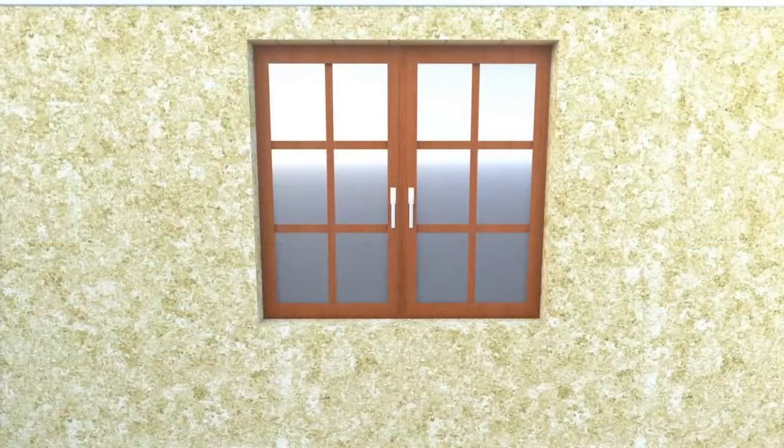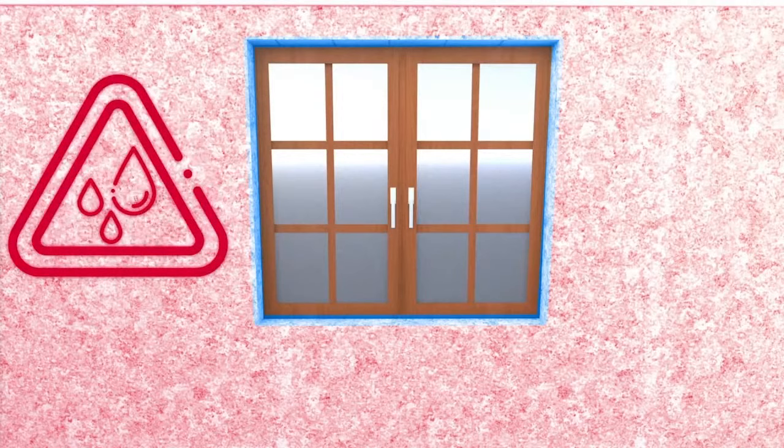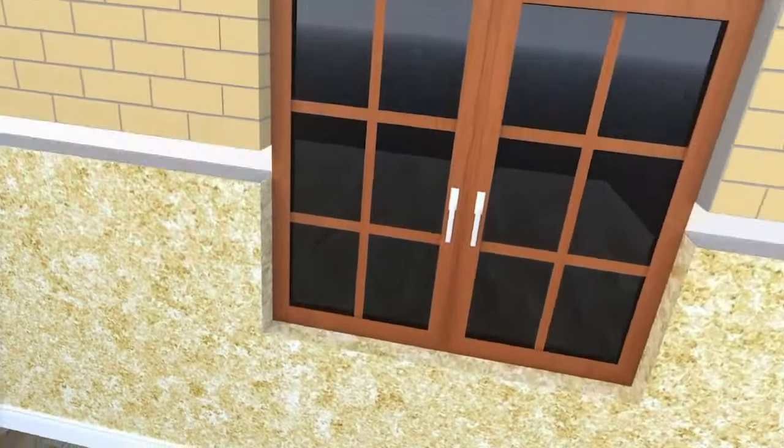In locations such as window reveals and door openings, it can be difficult to maintain a similar level of insulation to that found over the main sections of a wall, leading to these areas being relatively cold. In extreme cases, this can cause the temperature to drop to the point where condensation may occur in these areas, and as fabric insulation levels increase, so does the importance of continuity and uniformity.